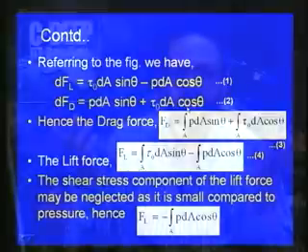So these are the equations which we consider for the lift force and the drag force, for which we consider an elemental area, and then we consider the normal stress or the pressure force, and then the shear stress or the shear force. With respect to the angle theta, we got two equations for the lift force on the elemental area and for the drag force on the elemental area, as shown in equation number 1 and 2.